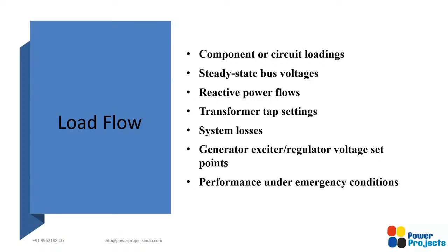Okay, fine. Moving to the second point, it helps you identify the bus voltages at each and every bus. Without performing a load flow, you may not be able to identify the voltage profile at each and every bus. So this is another important aspect of load flow analysis. Reactive power flow of course is covered as part of component or circuit loading itself. The load flow analysis is helpful to find out both real and reactive power flow, current, and power factor, in whatever sense you want.